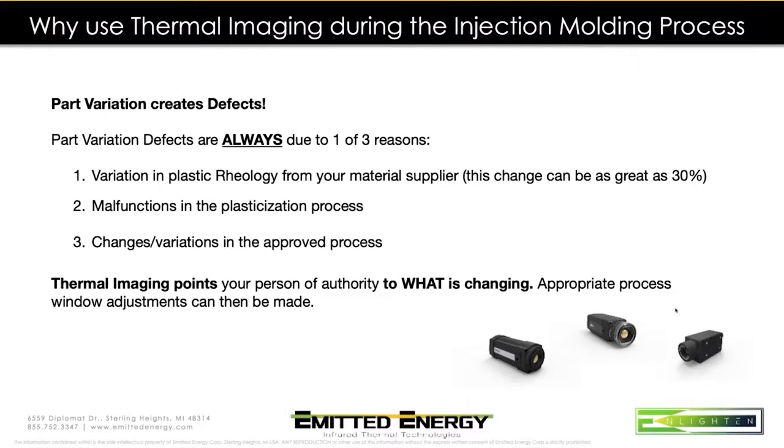The other thing that can happen is a malfunction in the plasticization process, and that's some of the things we talked about and will show you. You have a heater band, you have something stuck in your nozzle, you have water that's not working. Okay, that happens. Not as much as the plastic, not as ongoing as the plastic, but you will have things in your process that will start to have a problem. Okay, that's the second kind.